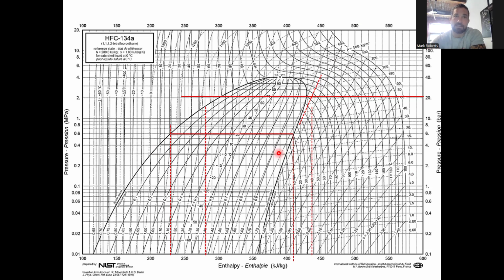Whenever I treat AC systems or vapor compression cycles, which would be AC or refrigeration processes, I like to start on the saturated vapor side. This is the material that goes into the compressor. So we first start by compressing. I'm going to follow these constant entropy lines until I compress it, and I need to pick a temperature. I want to compress it to a temperature that I can exchange with my environment, so I need to be hotter. If I'm a refrigerator, I need to be hotter than room temperature.